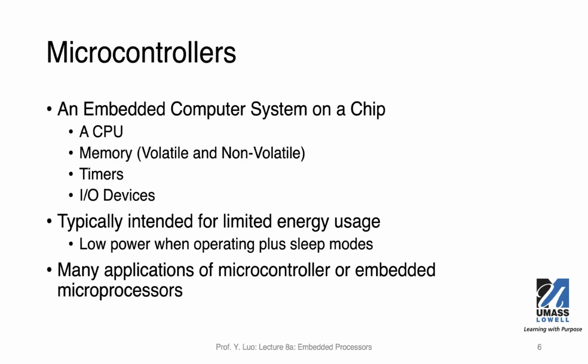And on this chip, you have a lot more components than a general purpose processor, for example, timers and I/O ports, or UART controller, or even USB controller on the same chip. So this is the so-called system on a chip. All the things you see here on the list, you don't have to have these components separately on the same PCB board. Instead, in modern microcontrollers, you have everything on this list embedded in the same chip.